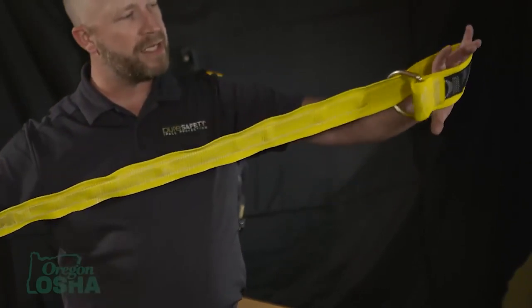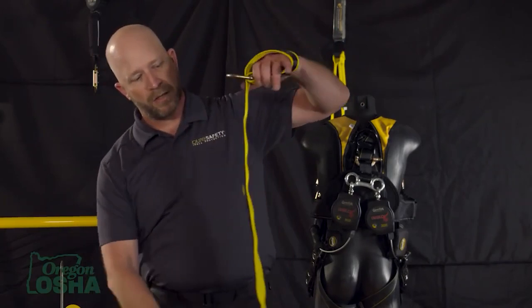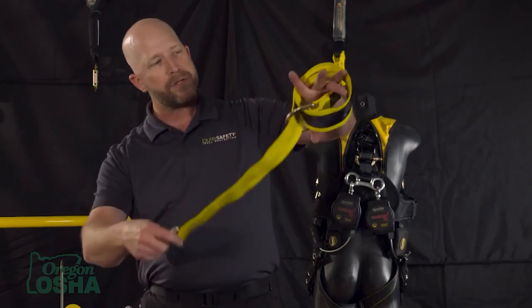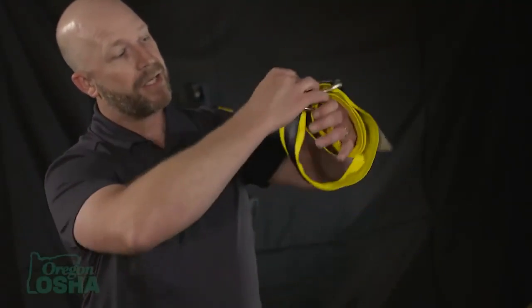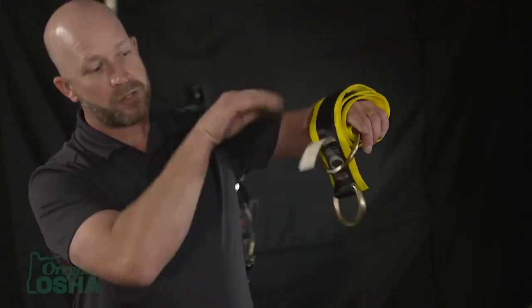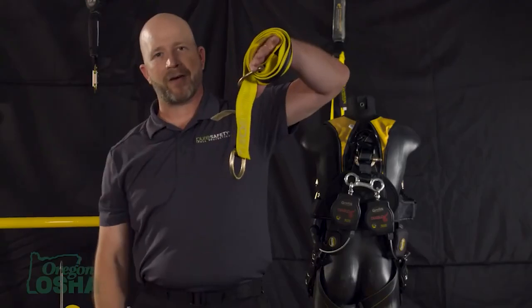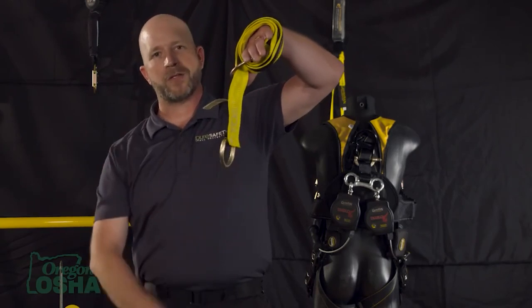The other benefit is that although it is as strong as it needs to be in this configuration, they are designed so that if necessary, you can do multiple wraps. Just make sure that it always pays through all of the way. That way you can get the connection as close to the anchor or the structure as possible. Just make sure you get a full choke through. Make it line up, and then we get it in tension, and it will hold its position, and then we have a correct or a compatible connection for our anchor or lanyard to be connected.